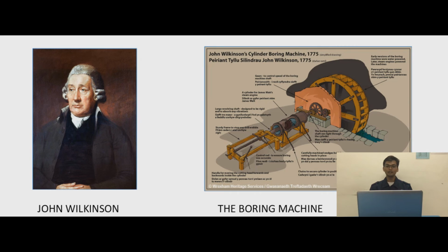Steam locomotive engines do not produce constant torque. They will pulsate in speed and torque during a single cycle. This causes vibration and jerky movement, which can cause inefficiencies. We can reduce this with the use of a flywheel, which stores rotational energy with inertia and evens the torque out.